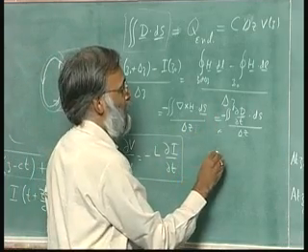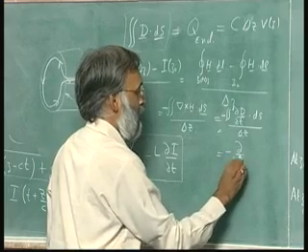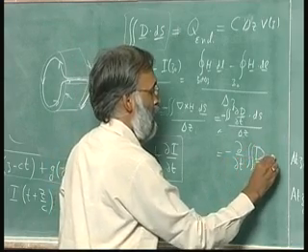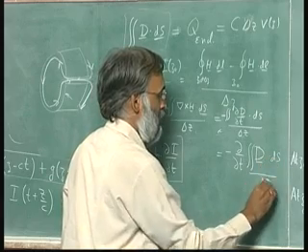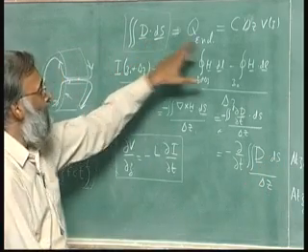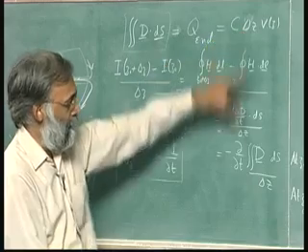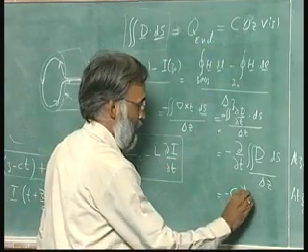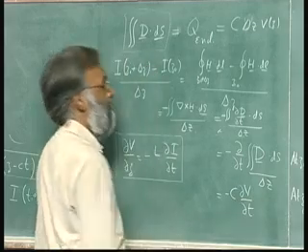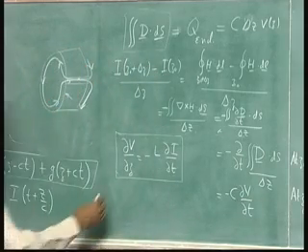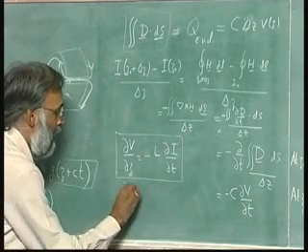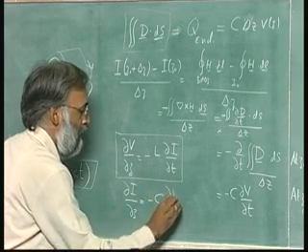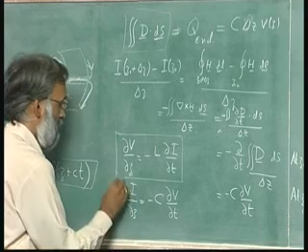So what you get is therefore minus del del t of surface integral d dot ds divided by delta z. I now apply this, the delta z cancels out, so that gives me minus c del v del t. So that gives me the second equation, which is del I del z is equal to minus c del v del t.